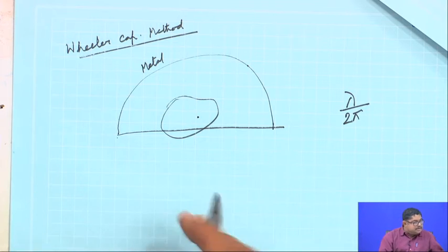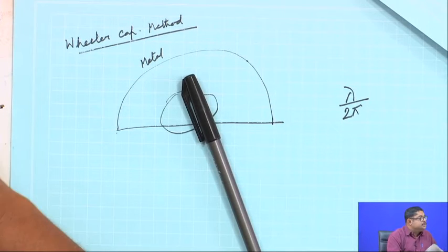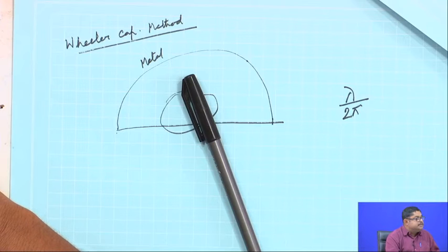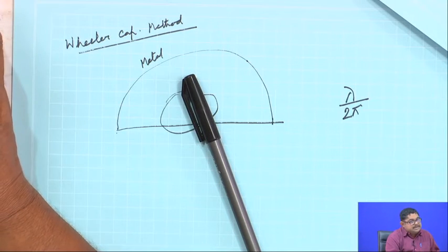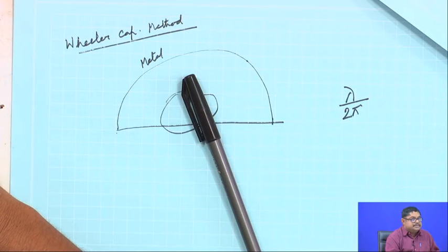So, what is done is, for any antenna, there is a feed, then after that we are assuming that there is a loss resistance. The antenna starts after the feed line. So, what is the antenna model? It is a resonating structure, so it has L, C, R, and this is the loss resistance. This R comprises both radiation resistance as well as the loss resistance.